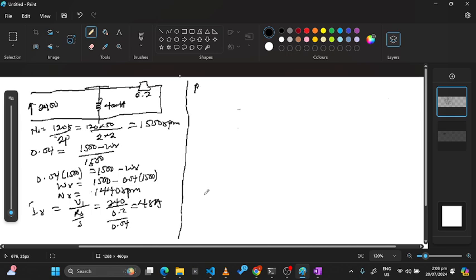So then if this is equal to 48 amps, I can find my total mechanical power. That should be equal to 3 times (1 minus S) all over S times IR squared times RR. So this should be equal to 3 times (1 minus 0.04) all divided by 0.04, times 48 squared, times 0.2.